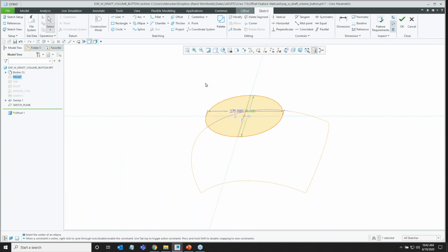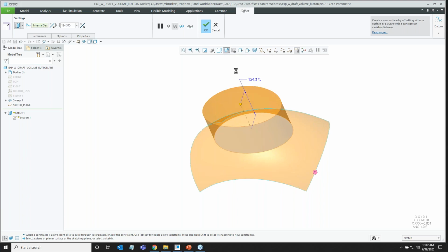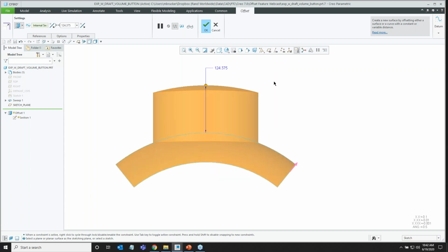So now the computer is going to project that sketch down onto the surface and then do the expand only inside of the sketch. It's going to expand part of the surface. So I go ahead and finish that sketch, and then I can see my expand feature is expanding just inside of that sketched region. Let's look at a 2D view here, a front view. And I can see in the front view, it's making the expand, and these side surfaces of the expand are normal to my sketching plane.